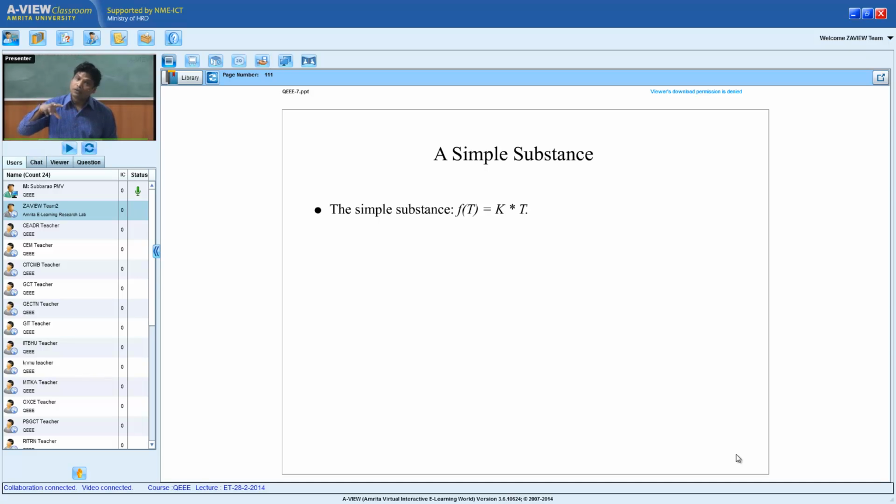And as I said, the only thing I can measure is the length. Suppose the temperature can produce a length effect, I can measure it. What did I select for that? I have selected the volume expansion of liquids. The moment I select the volume expansion of liquid, whenever there is a temperature change, the volume decreases or increases. So a change in volume is directly proportional to the temperature effect. So actually I say I have measured the temperature.